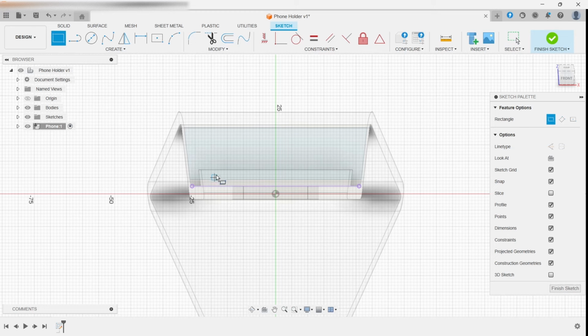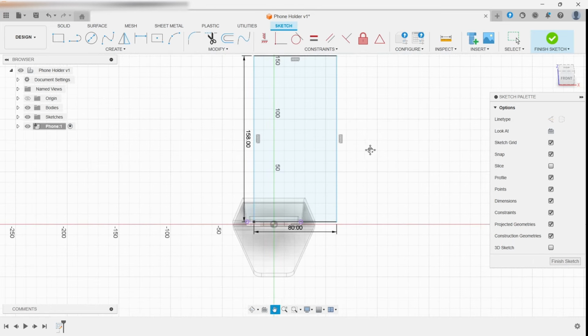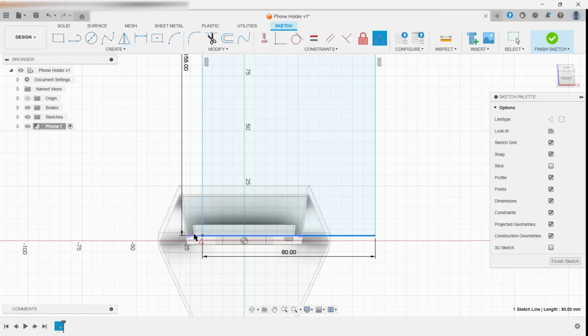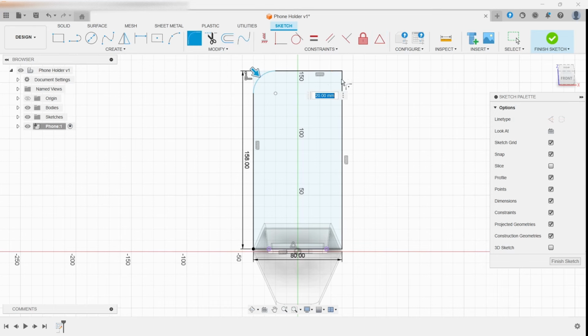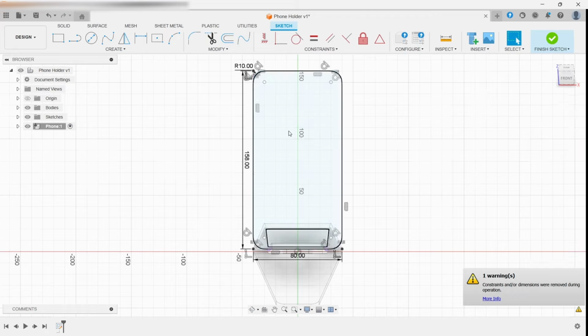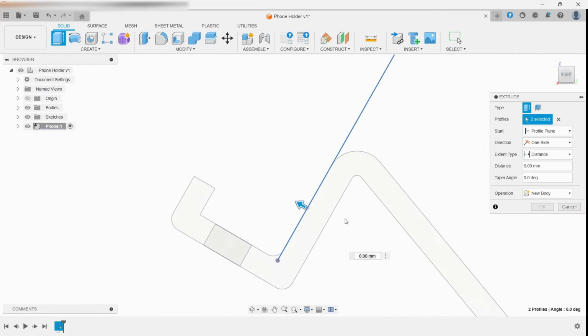In this case, the phone is an A51, so we can just get the dimensions online and then make a very simple mockup, just a rectangle with the right dimensions. After all, we don't need anything fancy. In CAD, in general, less is more, since the more complex you make the sketches, the harder it will be for you to change them.